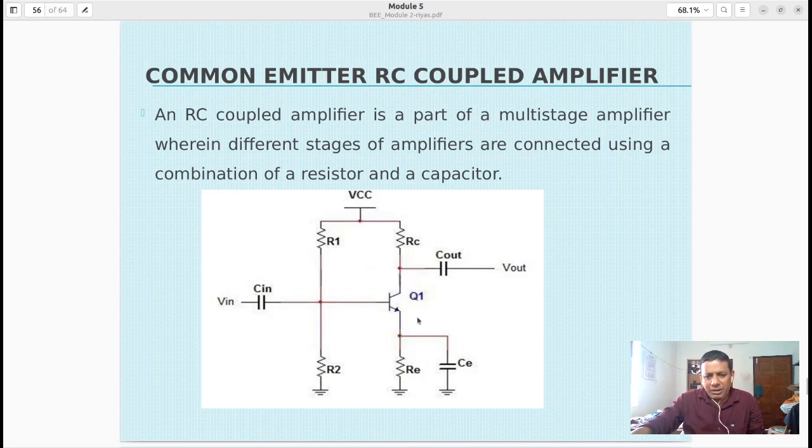but an AC current change will be there, and for AC, RE should not give negative feedback. So the AC signal has to go through C. C will reduce the negative feedback due to the RE, and C is known as an emitter bypass capacitor. Bypass means bypass, you might have seen Thrissur bypass, Calicut bypass, Ernakulam bypass, etc. Similarly, the AC signal has to pass through this C. RE will provide negative feedback for both AC as well as DC, but for AC it should not give negative feedback. So that AC has to bypass through this, that is why we are giving this C.